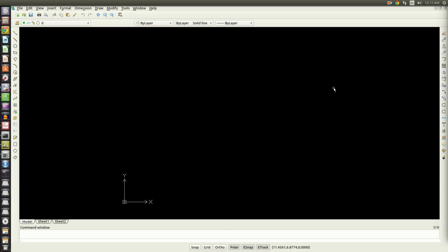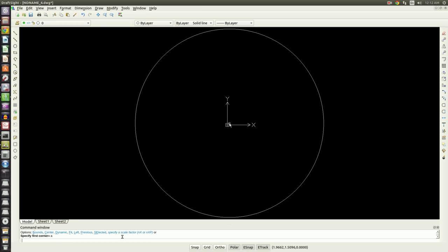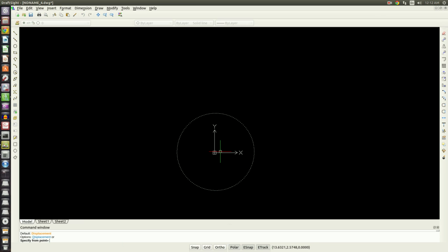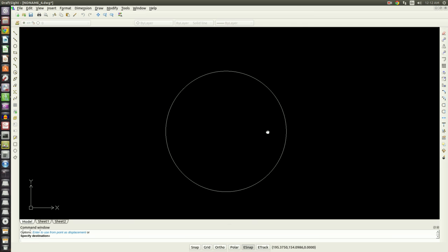If you notice, the biggest diameter, or radius rather, in the drawing is a 92 millimeter radius. So let's jump back over to model space here, and I'm just going to pick a circle out in the middle of nowhere and give it a 92 millimeter radius. And you notice it jumps off the screen. To fit it into the screen, I'm going to type zoom in the command line down here, hit enter, A for zoom all. And now the whole circle's fit into the drawing. I'm just going to move it outside the user coordinate system just so it's not in the way in the middle of the drawing again.